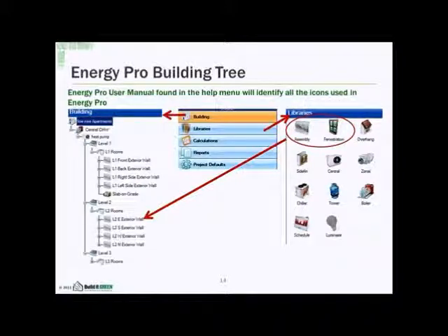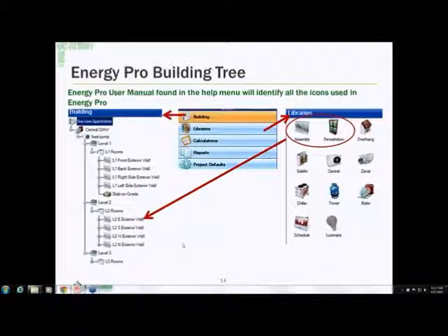I just think that the building should be best representative of what you find. And as far as Energy Upgrade California or Greenpoint Rated, it's most likely you're not going to be doing anything to these common areas. But I think it's a good idea to include it, just for the sake of getting a good load analysis. And again, if this common area is separate from the main building where all the residents are living, then don't model it.